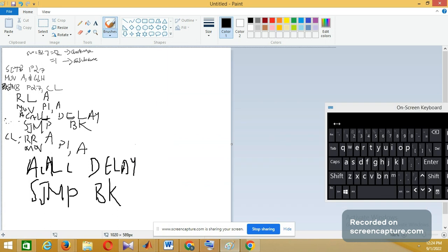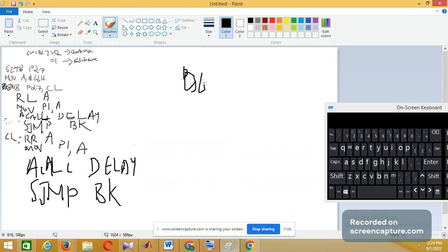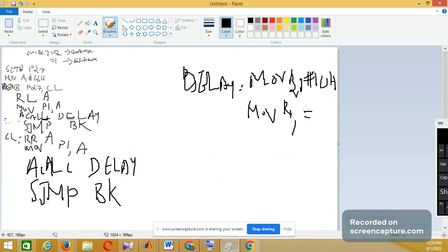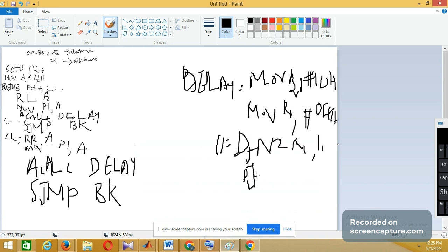So delay subroutine: MOV R2, #10H; MOV R1, #0FFH; DJNZ R1, loop 1; DJNZ R2, loop 2; RET. This is one chance.